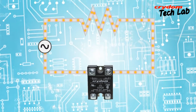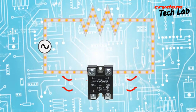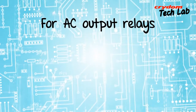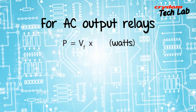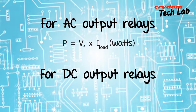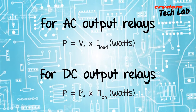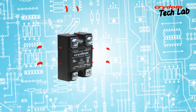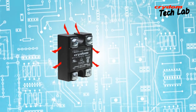All SSRs and SSCs utilize power semiconductors, which generate power as a result of their on-state voltage drop or resistance when carrying load current. For AC output relays utilizing thyristors, power measured in watts equals forward voltage drop times load current. For DC output relays utilizing field effect transistors or FETs, power measured in watts equals load current squared times on resistance. To ensure reliable operation of the SSR or SSC, this power must be dissipated into the surrounding environment so that the relay operates below its allowed maximum temperature.